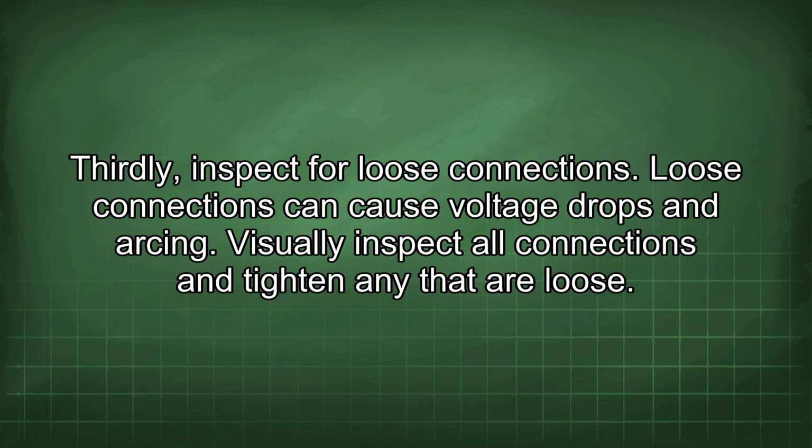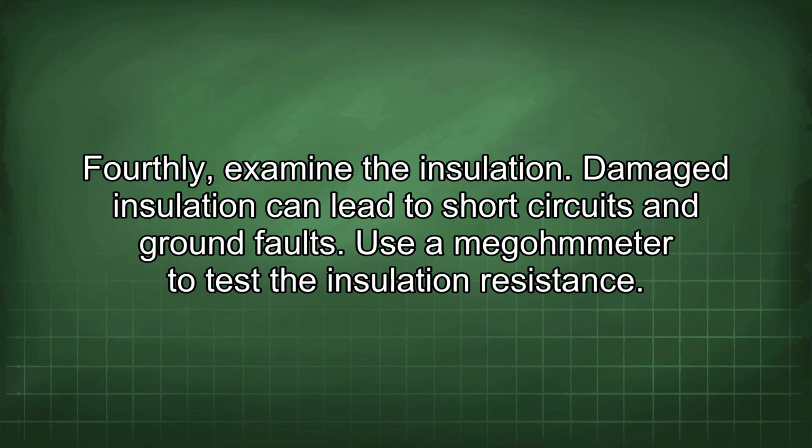Thirdly, inspect for loose connections. Loose connections can cause voltage drops and arcing. Visually inspect all connections and tighten any that are loose. Fourthly, examine the insulation. Damaged insulation can lead to short circuits and ground faults. Use a megohmmeter to test the insulation resistance.